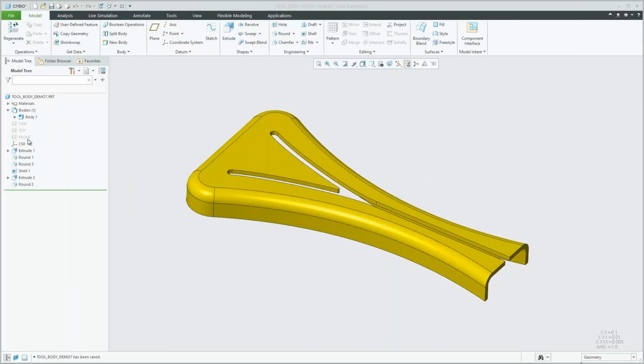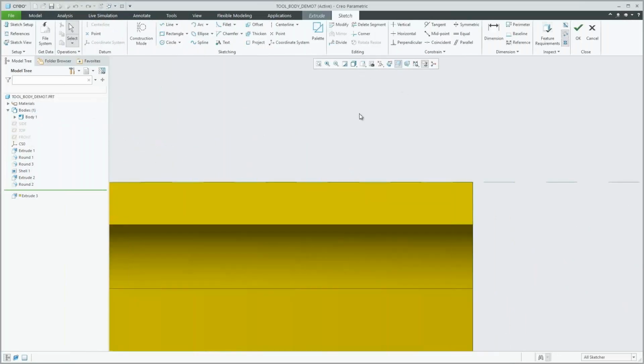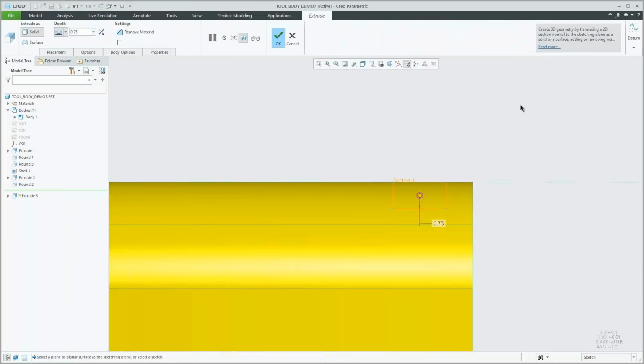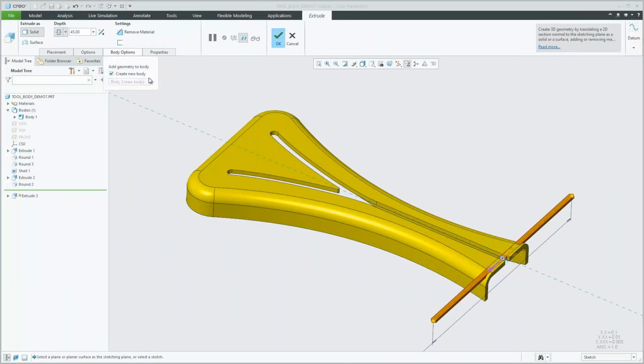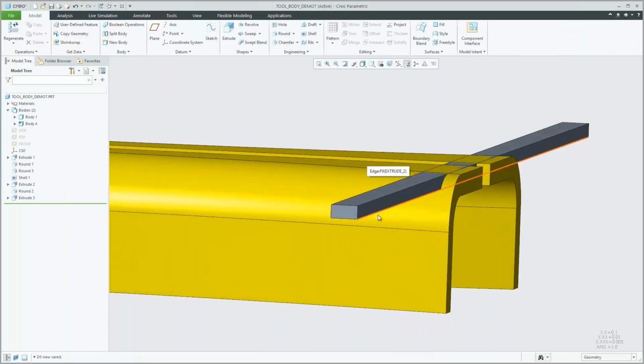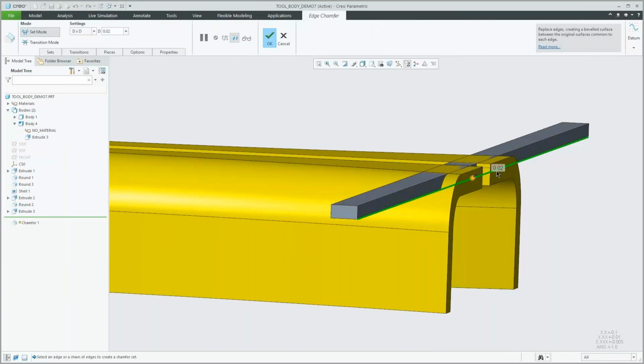One example is things that you have to make complicated surfaces for, especially if they're construction geometry. It's much more effective to make it as a solid body because it's just easier to work with, easier to think about. So for example, this is the part that you saw in the PowerPoint. You have this yellow piece, you want to create some grooves in it, create a piece, and then select new body. So this is no longer just an extrude, this is a whole separate entity.